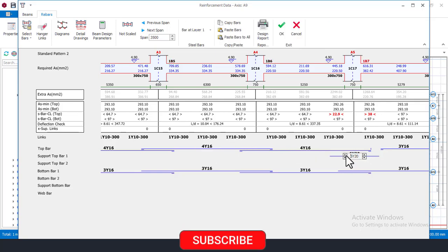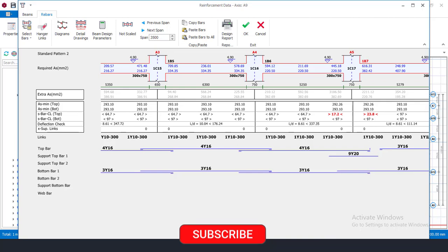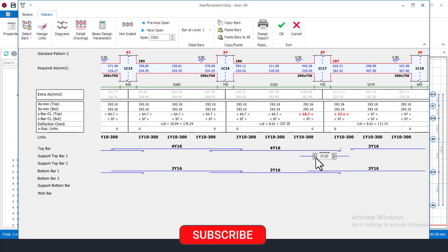You can see that here I was showing 9Y20. That is why you must check your bars. Check your bars, but the software might perform over design, which is not okay at all. So make sure you check your bars, okay? Check your bars, guys. Come again right now, click on this. So click here and reduce this, okay?